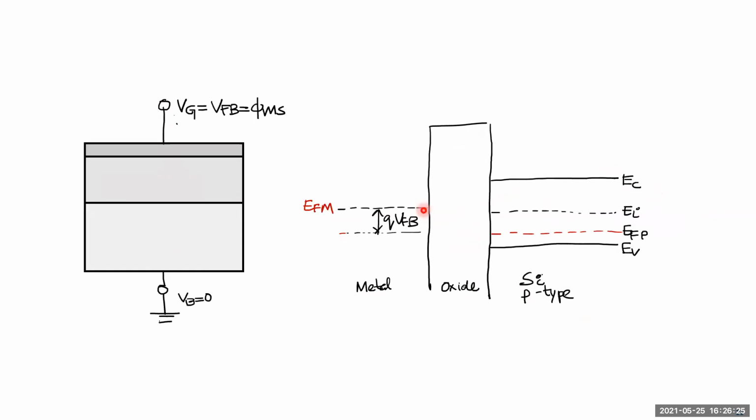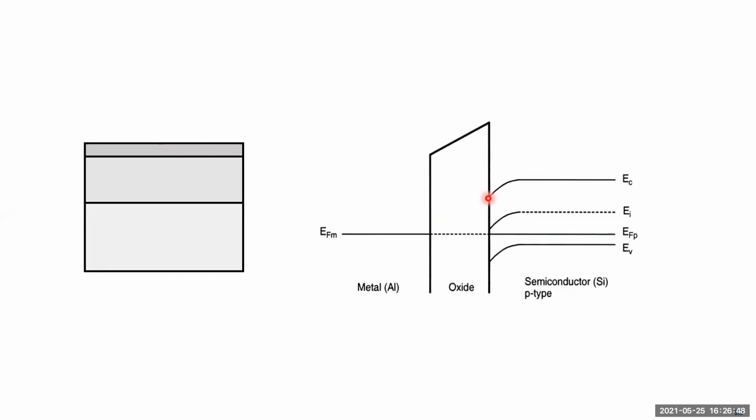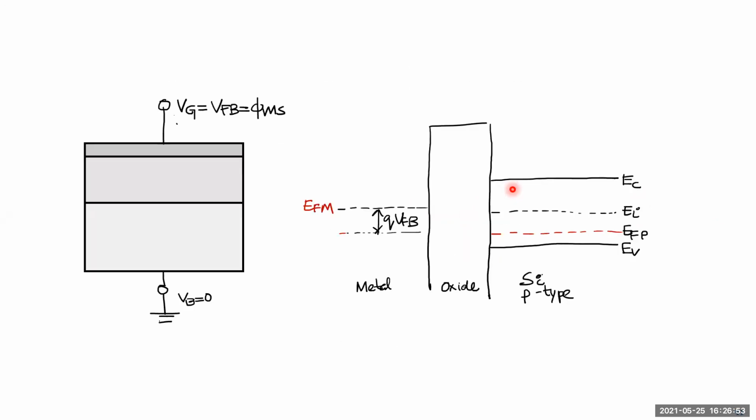Now you apply a voltage such that these bands get flattened. Now you can see there is a difference between the Fermi potential. That's your whatever band potential. So the Fermi potential by definition for a steady state needs to be the same, but now it's not steady state anymore, because we have applied an electric field across it. Whatever the difference was in the bend, that voltage difference we apply across to flatten the band. And that's why it's called flat band voltage.